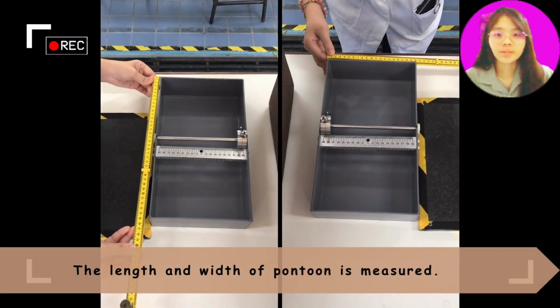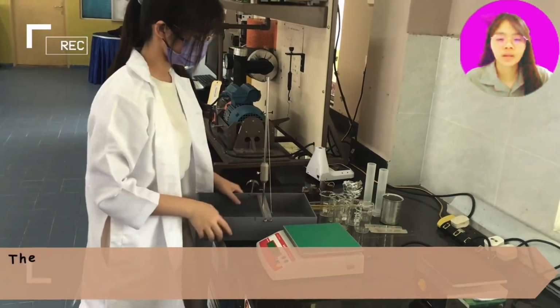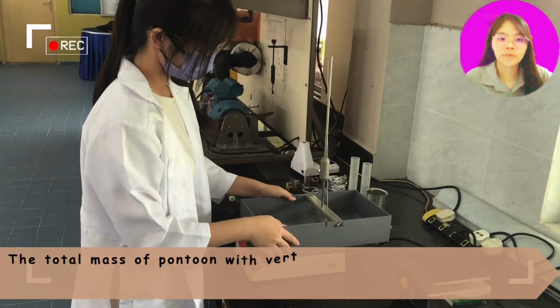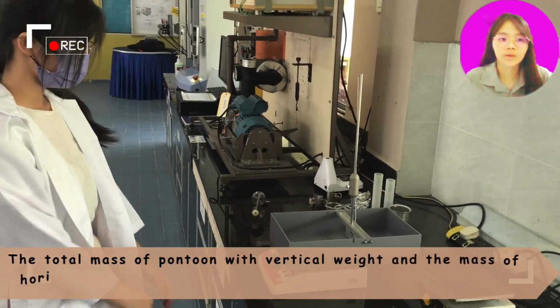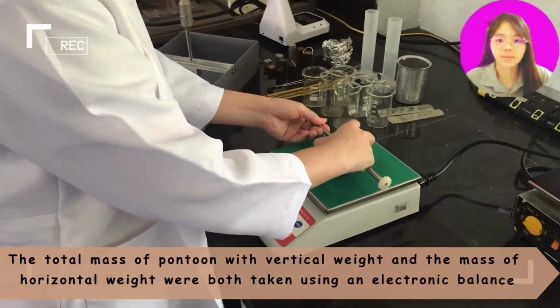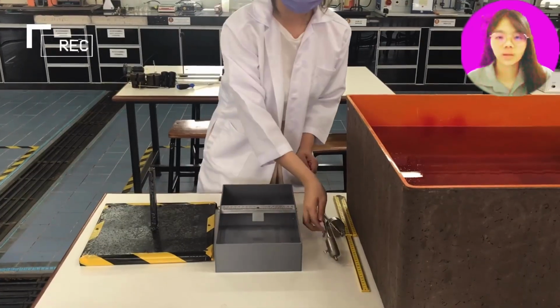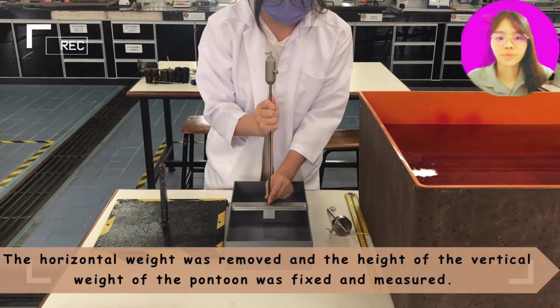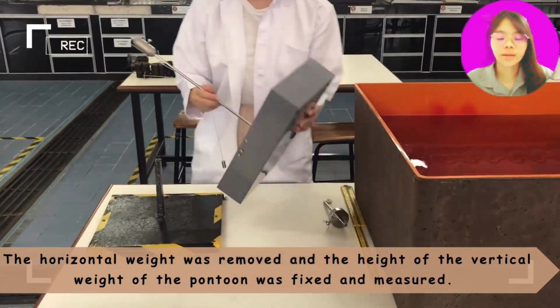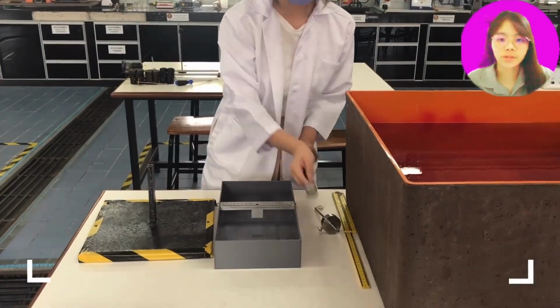The first step is to measure the length and width of the pontoon, and the total mass of the pontoon with vertical weight. The mass of the horizontal weight is also taken using an electronic balance. The next step is to remove the horizontal weight, and the height of the vertical weight of the pontoon was fixed and measured.